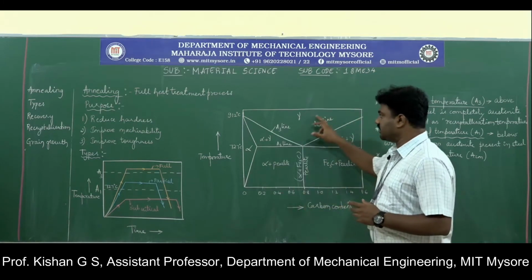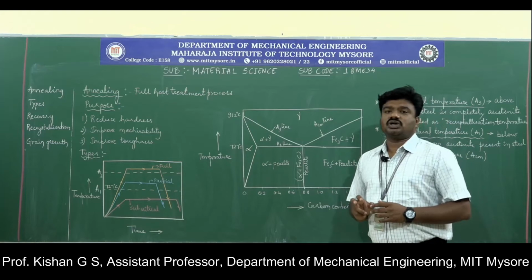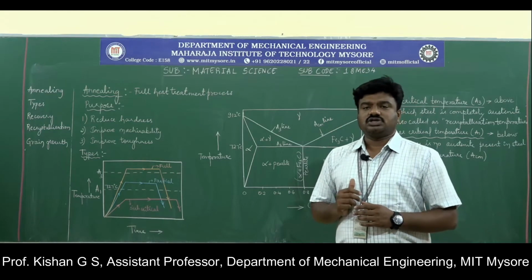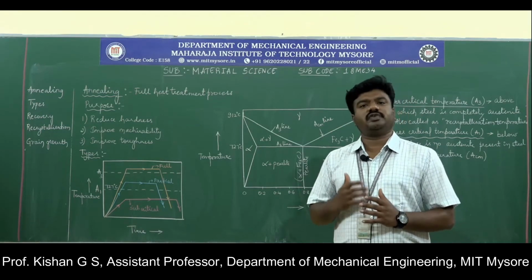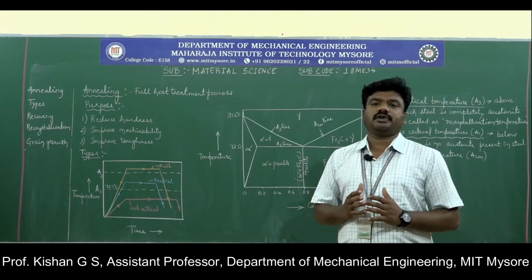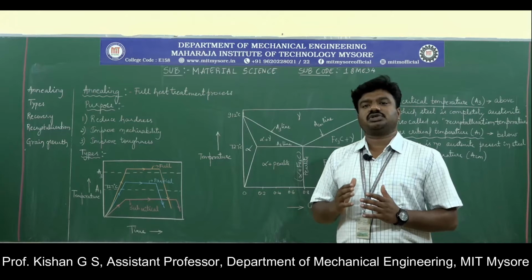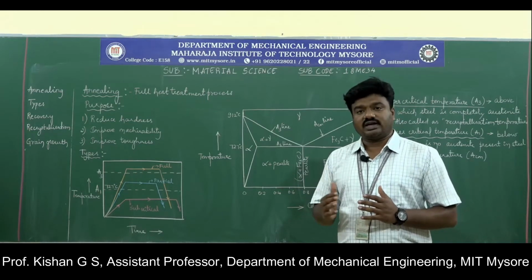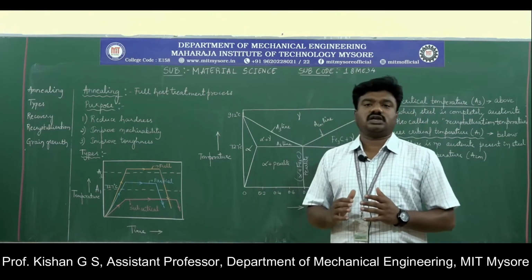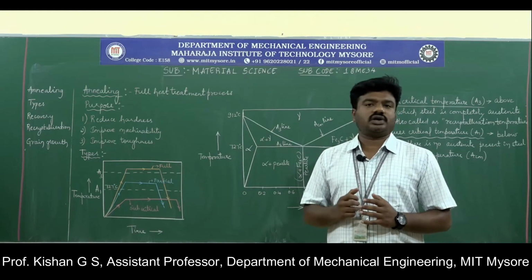Okay. And the third point is the ACM line, which represents the cementite line that goes with the temperature that leads to the formation of eutectoid composition in the representation. This is specific to whatever composition we take, but uniquely we have to target the upper critical temperature and lower critical temperature in any composition, wherein the upper critical temperature leads to the identification of the austenite phase above it, whereas in the case of the lower critical temperature, you are not going to get austenite solution below it. So this is what we call the upper critical temperature and lower critical temperature.